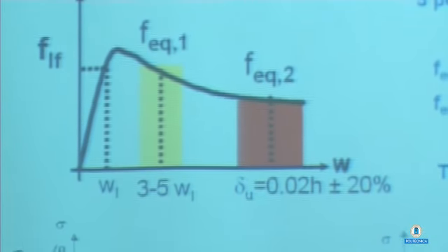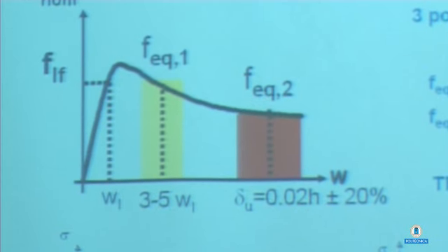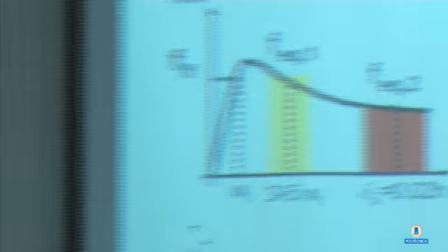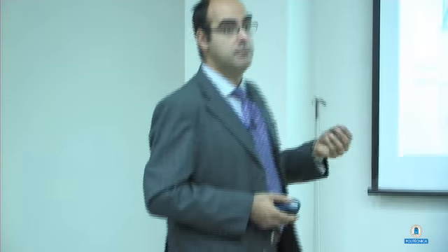There is RILEM, which has been accepted as an EN standard, and they prescribe a notched beam specimen in 3-point bending. We have in Italy a notched beam specimen in 4-point bending, a little bit different. But those specimens are 150 millimeters deep, and there is a notch which triggers the fracture in one section. When you go with this kind of application, very thin slabs, the notched beam specimen is not representative of what would happen. So in our guidelines, and it is going to be accepted also in the new version of the Model Code, they speak about a structural specimen, a specimen which actually reproduces the structural element to be manufactured.